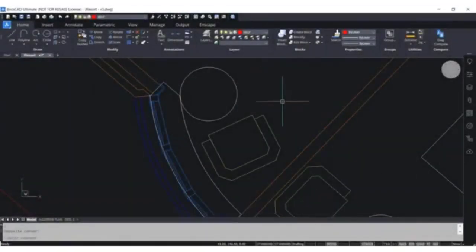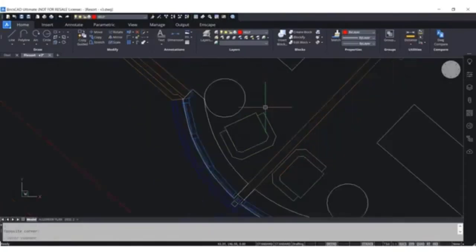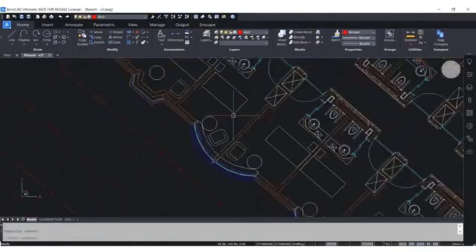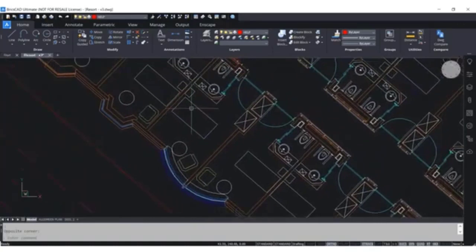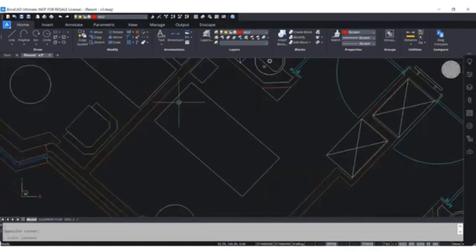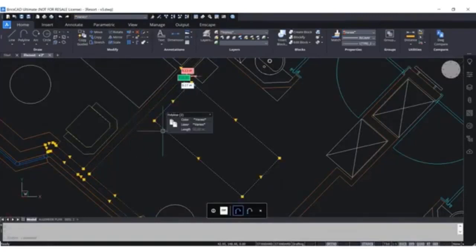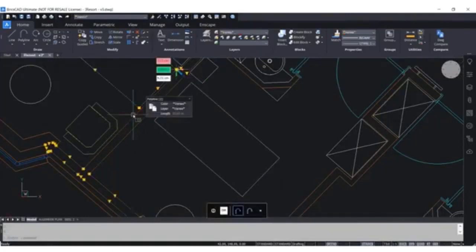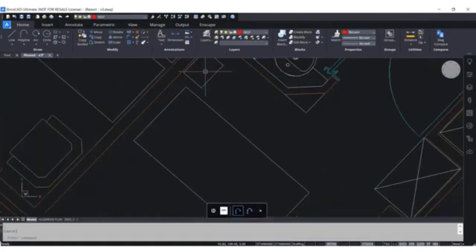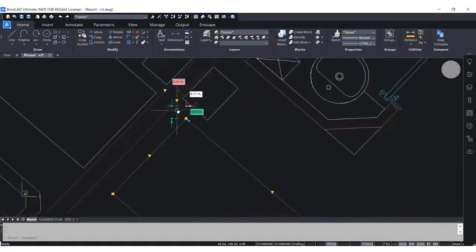When using BricsCAD, we can often interact with its data. I will show you an example by using the nearest distance feature. This feature allows you to quickly see how two entities relate to each other in distance and eventually edit them, if necessary. You can see that when I select these two entities, I get 3 different values along with colors. The red corresponds to the x-axis, the green to the y-axis, and white is the overall distance. If you're 3D modeling, it will also display blue for the z-axis.